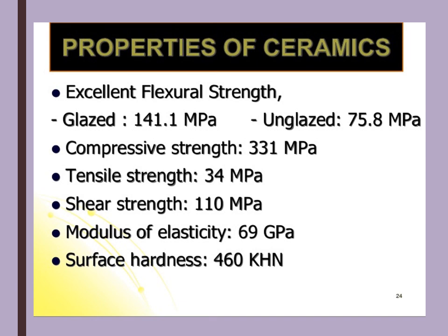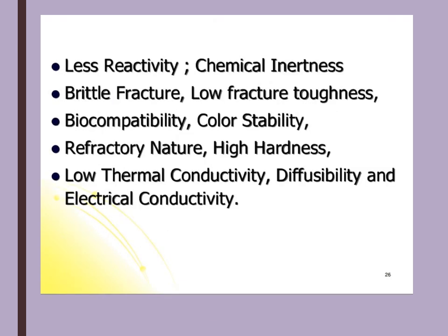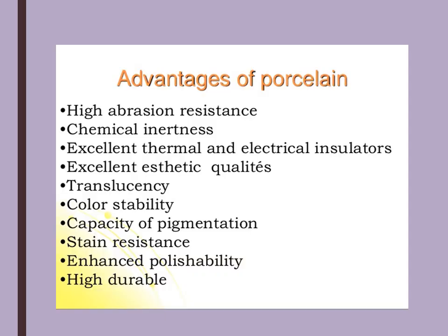The hardness is very good. It's 460 Knoop hardness. It is chemically inert, less reactive, so it is stable in the oral cavity. Brittle fracture, low fracture toughness because it's brittle. It has excellent biocompatibility. It has excellent color stability. It does not discolor or stain over time. Refractory nature, it is able to withstand high temperatures, high hardness, low thermal conductivity. It's an excellent insulator. Diffusibility and electric conductivity are low, and it has a coefficient of thermal expansion closer to that of enamel and dentin.